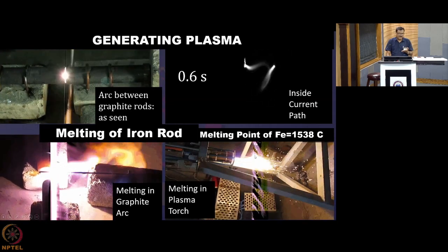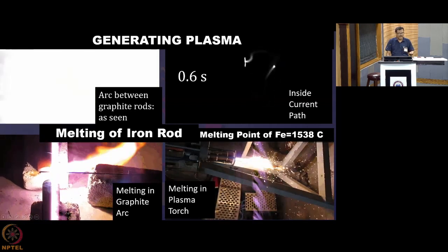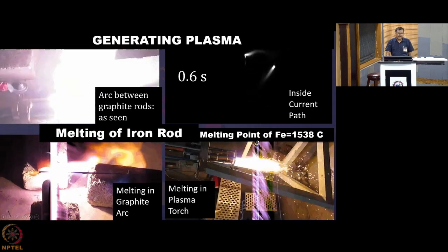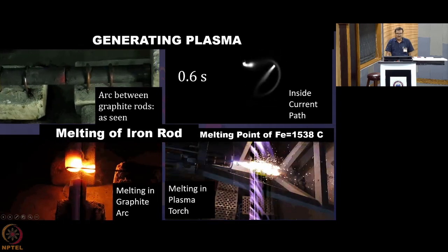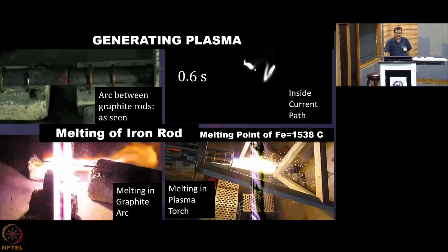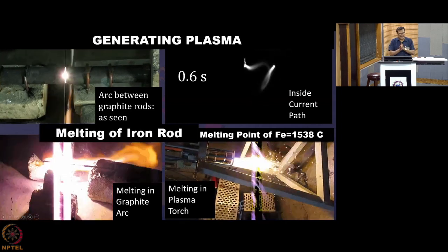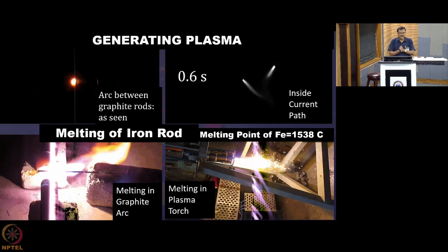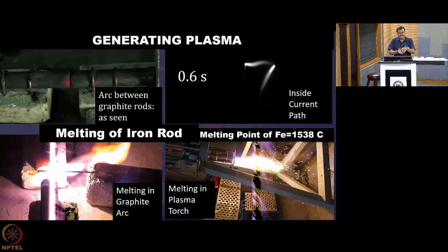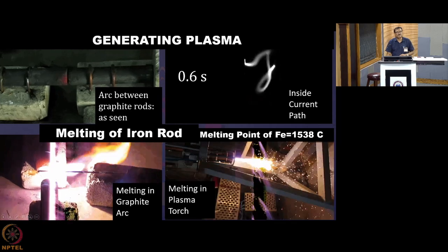Now, as a proof, I have recorded this video. This video is recorded in an ordinary camera, and what you are seeing, the same rusted rod that I put over here, I have taken and inserted a bit below this flame. The arc, which was moving very randomly, is now very much stabilized, through thermal pinching, and because of the cold boundary layer, it is pinched near the central axis of this plasma torch.